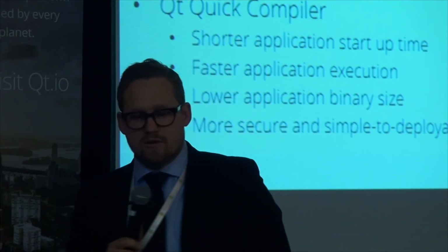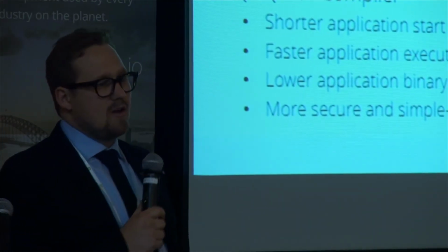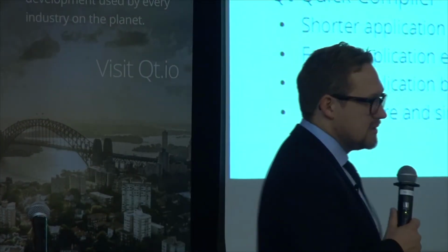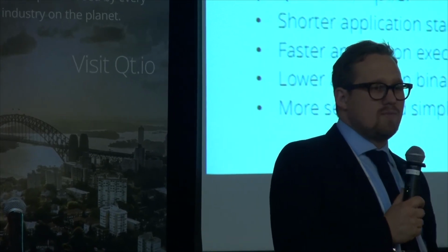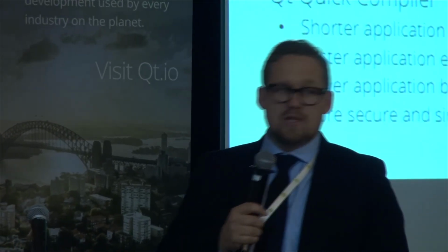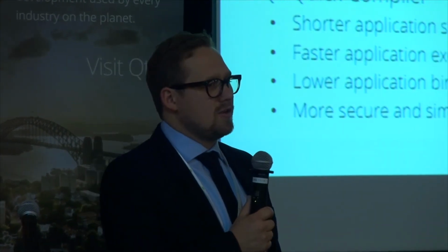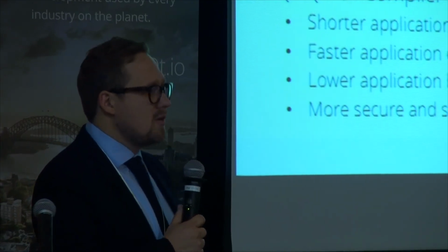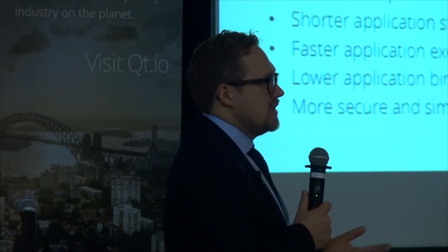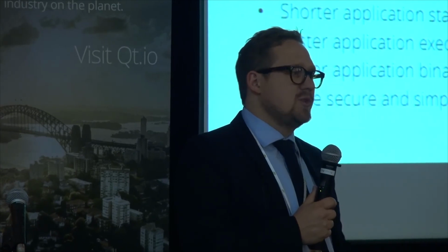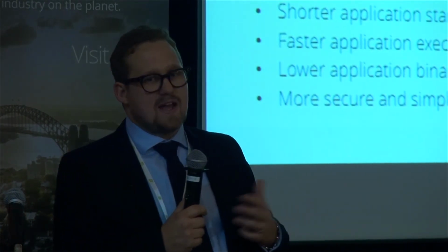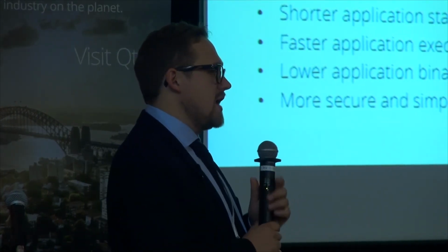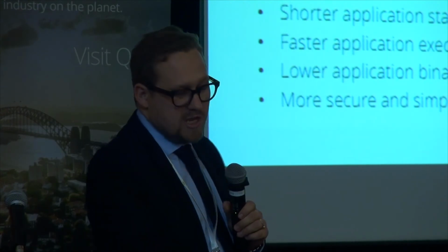And the Qt Quick 2D renderer is a way for us to actually render your UI without OpenGL. That's something we haven't touched too much upon yet, but Qt 5 is really based on OpenGL. So a lot of people have come to us and asked, hey, I want to have an embedded device with no OpenGL. We don't need fancy 3D graphics. We don't need these super fast animations, etc. So is there some way we can create Qt UIs without OpenGL?